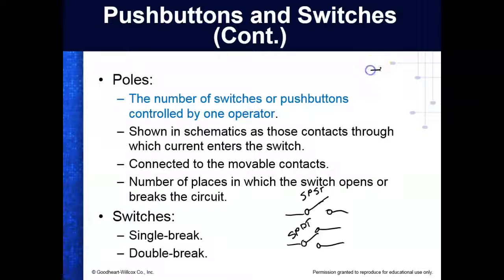And then if I came over and did this, and then I put a symbol that says these are mechanically connected together, and it's a dashed line. So all I would see is one switch, right? You understand? This would be a double pole, but each one of them can only control what? One circuit. So that'd be a double pole, single throw. Two poles, I'm controlling two switches, but each switch can only control one circuit. Okay.